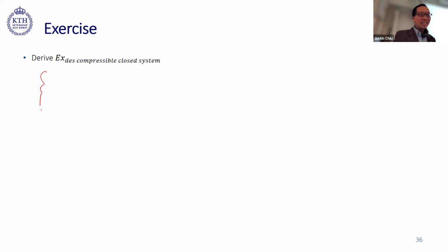Here again, let's list down everything we know. We know by definition, heat and work, conservation of energy. This one is a closed system, so Q plus W is equal to the change of internal energy. That's just a definition. And then also by definition, what is Q? Earlier we said T times dS, so the entropy is squiggly Q divided by the temperature.